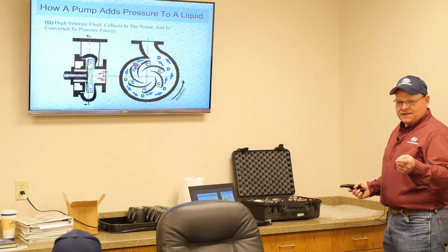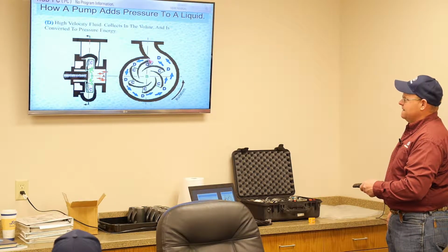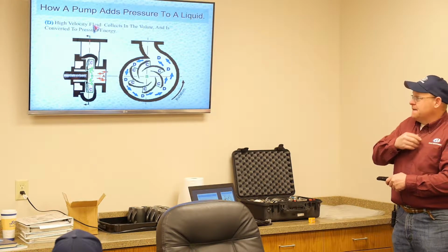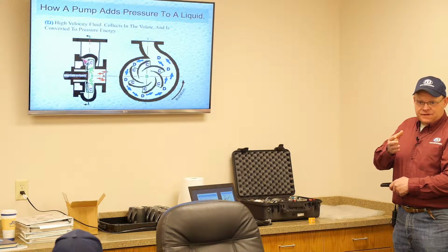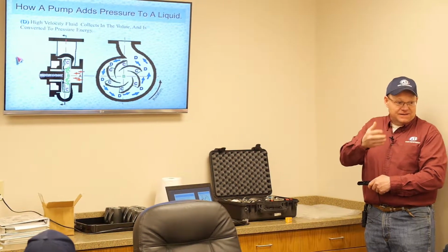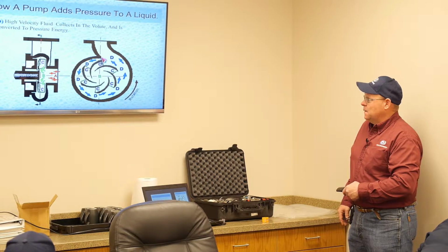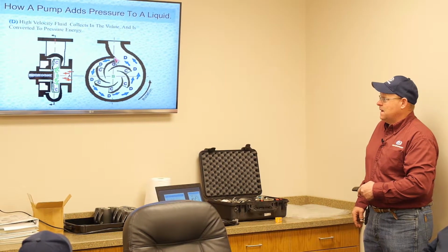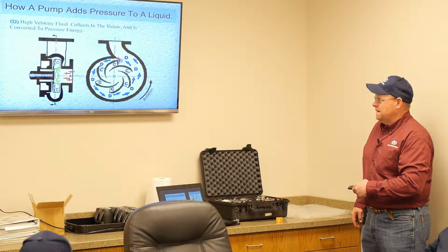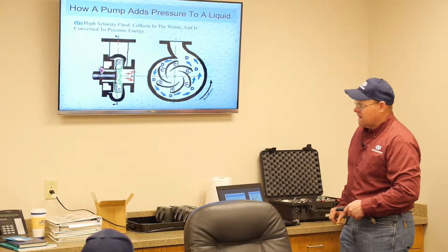As you're tearing down and inspecting pumps, be aware that this is going to be a high point of wear. Particularly, Ty, for you where you have a solids laden fluid. For you guys, new well comes in, lots of sand. This is going to be the point where the oil, fluid, whatever you're pumping is going to wear out right here, one of the places. So just be aware that that's going to be your high pressure point in the pump.